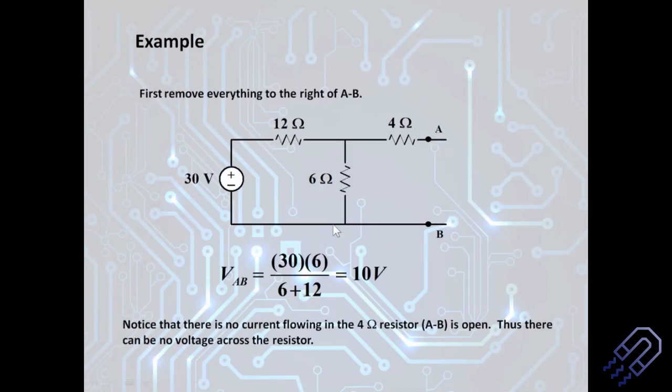Okay, it's very easy. We have got a simple circuit with voltage and two resistances in series. So what is the resistance here? You see, this is the current flowing. There is no current division here because current won't flow here. The entire current will be here. So if here it is I1, this part also it is I1. So that means 12 ohm and 6 ohm are connected in series. So it's 18 ohm.